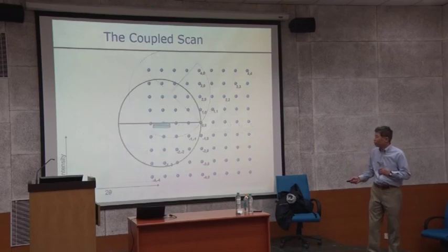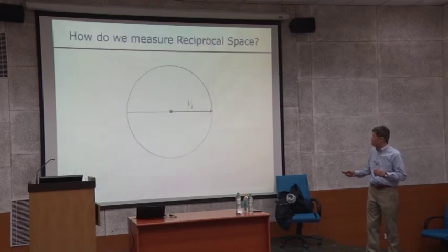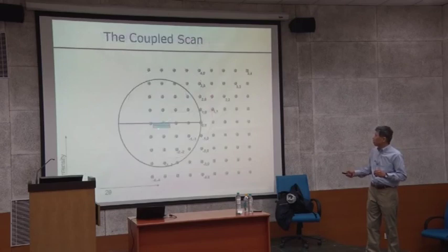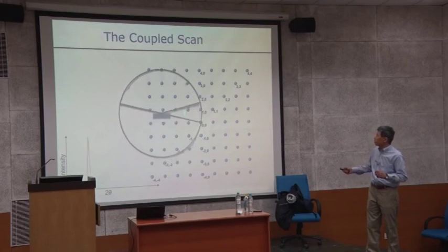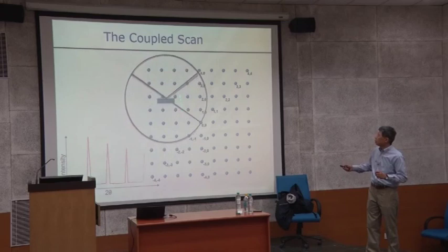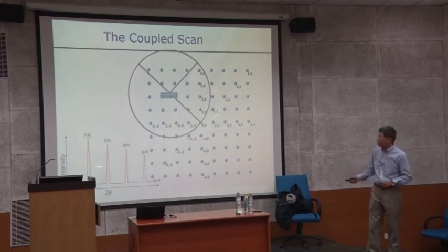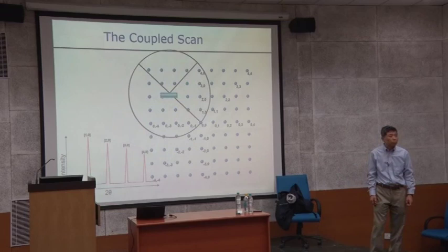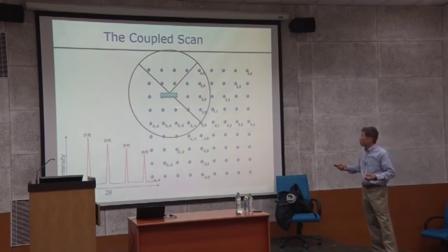But whenever you touch it, your theta angle will change, which is a 2 theta angle change. So you draw the 2 theta angle, right? The 2 theta angle increases, and then you get this peak. Okay, so this is a simple geometric description of all the diffraction conditions, and this one is for a single crystal material along this scan.